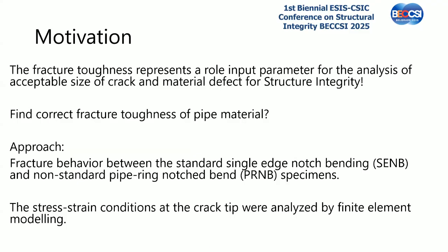So of course, in order to find the fracture toughness and to select a proper material, usually you have a standard test procedure like ASTM E1820 for 3-point bend or CT specimens, for the toughness. But we also need to compare with the values of stress-strain behavior, what we did.